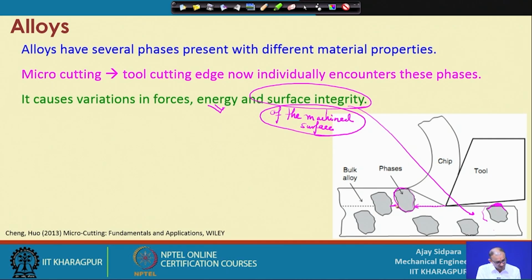Now, consider this is the grain. It is exactly opposite to this: only a small portion is located inside the workpiece, or inside the machining zone region, but most of it is within the uncut chip thickness. So, when the tool encounters this, the whole grain will go out. So, instead of a flat surface, you end up with a scoop or a cavity. So, this is what is happening in this case.